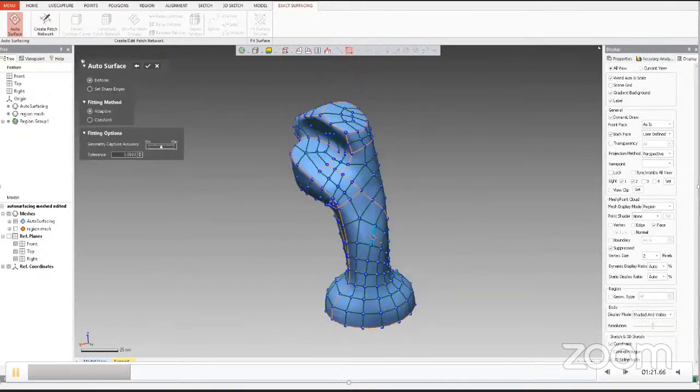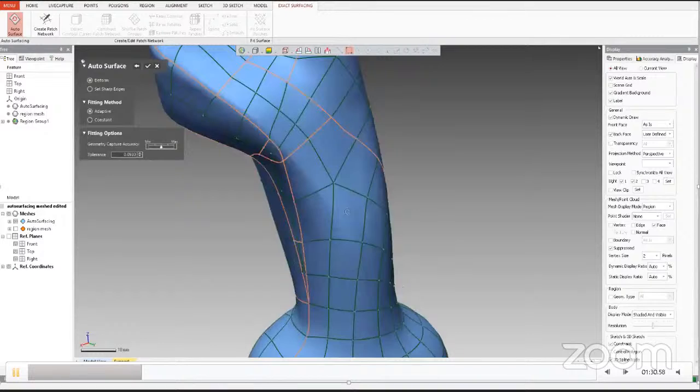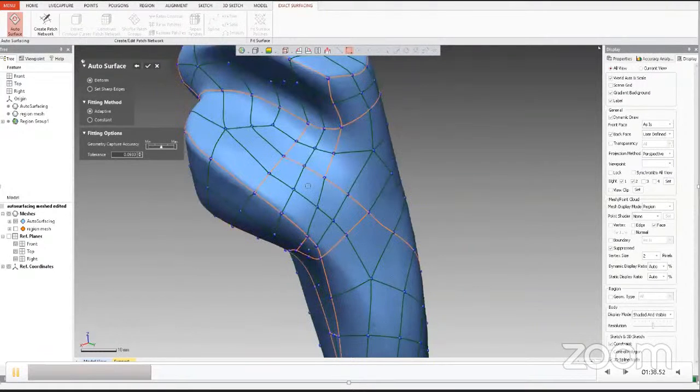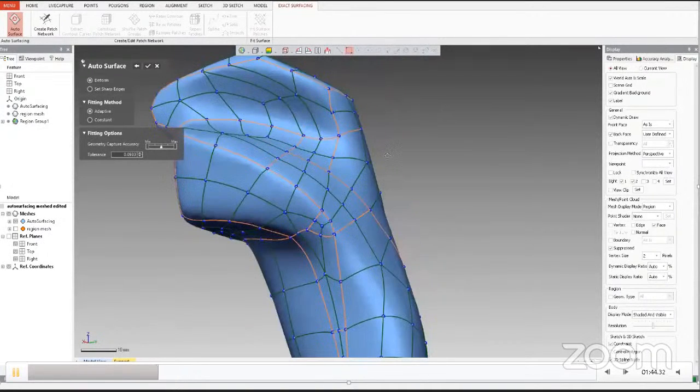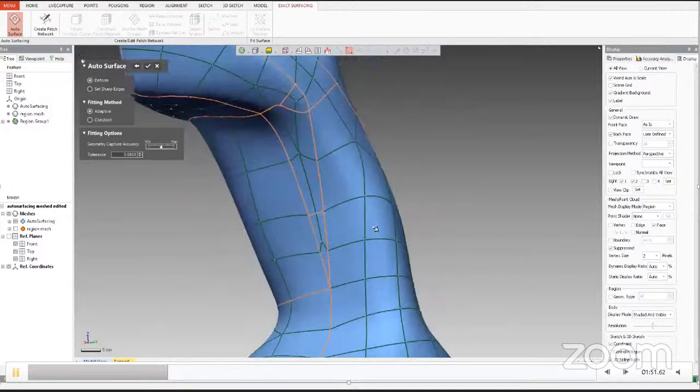So here we can see the contours have been generated automatically by this command, and we can see the small patches. What is so important about these patches is that they consist of 4 vertices. Every patch consists of 4 corners, and if we don't have a patch with corners equal to 4, we won't get the surface filled up to that patch. So we have to completely analyze, and this software with the auto surface will generate the patches with 4 corners. With the help of this deform option, we can readjust the corners based on our requirements.